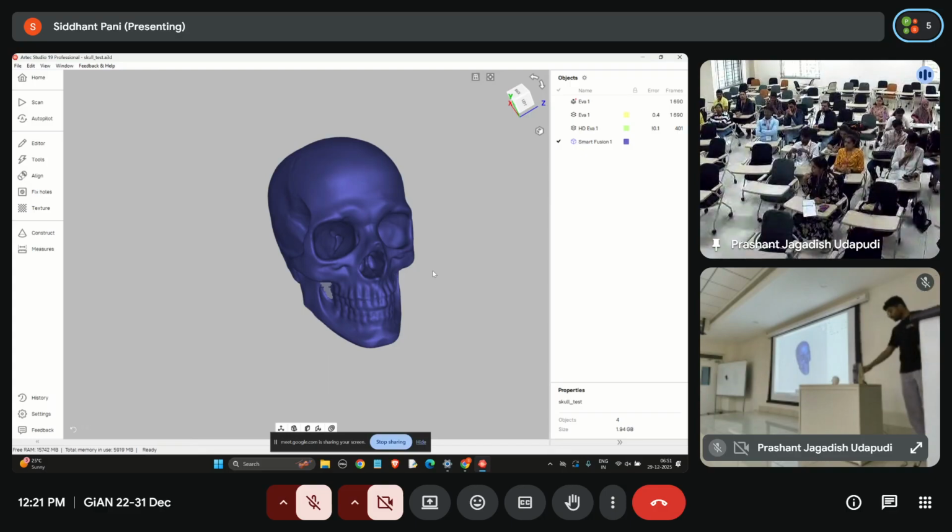Internal parts, because as you see we have to take the scan from different angles. And the distance is also something, you can see it tells you how much distance to keep. Since this is a structured light scanner, you need a well lit environment. The problem with structured light scanners is if the surface is too shiny, it won't reflect the projected pattern properly.